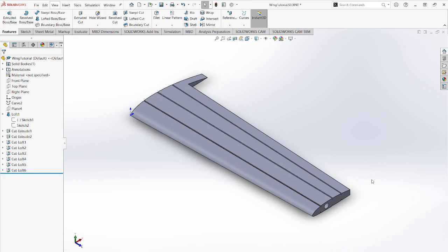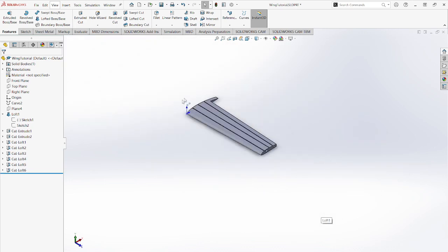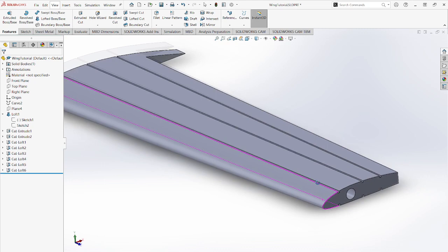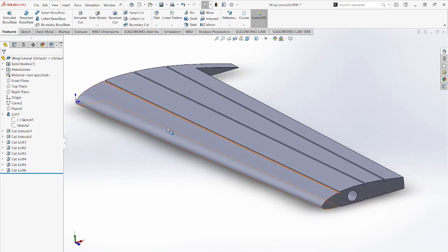Next, we're going to make the front skin to handle the curvature at the beginning of the wing. So when we create our wings, we essentially have a series of ribs, a carbon fiber spar in the middle, stringers, which keep the skin adhering to the curvature of the airfoils, but then we have this front area, which is really curved. And if we try to put the heat shrinking plastic on just that, it would want to suck into the gaps between each rib.